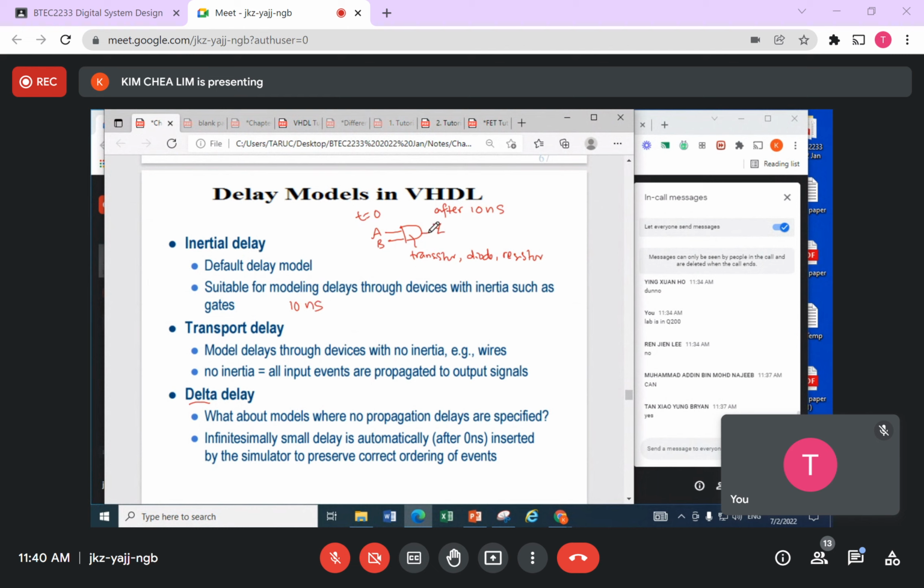So for example, now let's call this output Z1. This output forms the input of another AND gate, which has the C input. To get the correct output now, you find that you need 20 nanoseconds later, because the correct answer for the first gate is 10 nanoseconds. If there were no delay, the output would already be there, but it may give you the wrong answer.